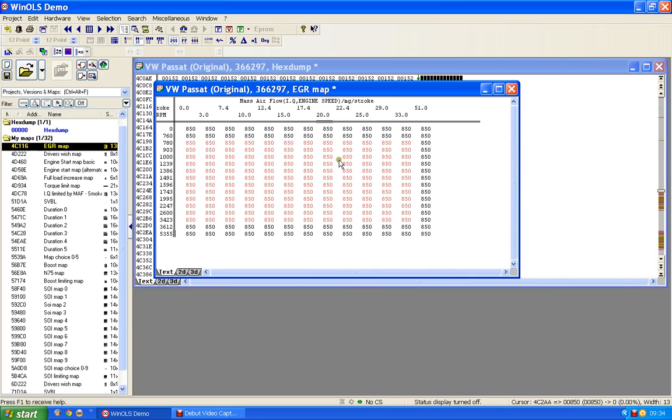And so you can't do this sort of setting on even quite old vehicles now, and you certainly can't use blanking plates to block off the EGR. You have to use another route to trick the ECU into accepting the fact that the values it's getting are perfectly acceptable, and this is not one of those methods that you can use.